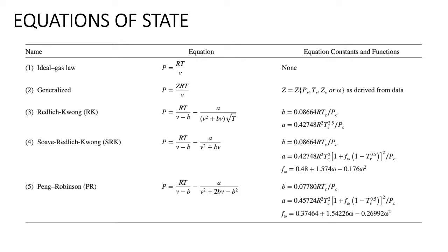However, we want to describe many systems with a good equation of state. So in here you can see Redlich-Kwong-Soave or Peng-Robinson. You also heard about van der Waals equation before. However, this equation is rarely used now because the application is quite narrow. So most of the time now we either use SRK or Peng-Robinson.